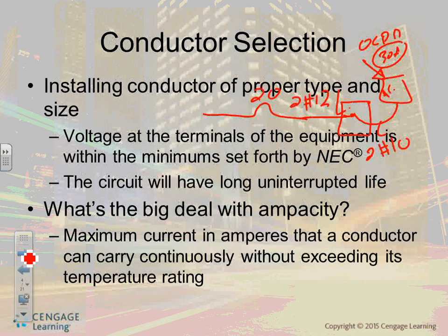Now, air conditioning, because it's a commonly used appliance, we use them all the time. Outside unit, they do not need a neutral. The manufacturer makes the compressor and the outside blower run at 240. And there are little control relays there, and I don't think they even have a transformer. Everything is running at 240. That's it. They don't need 120.